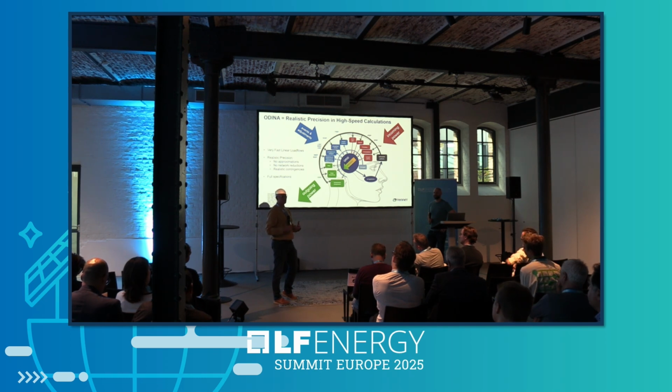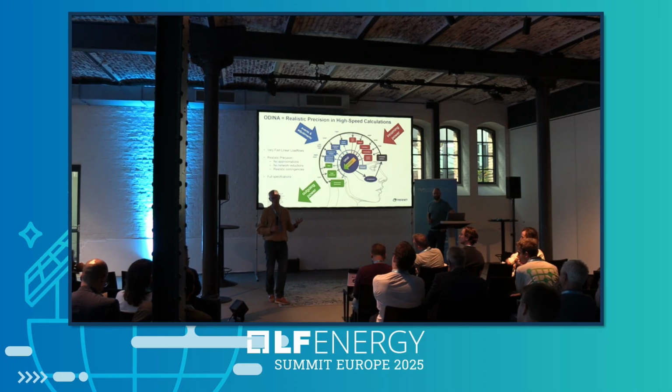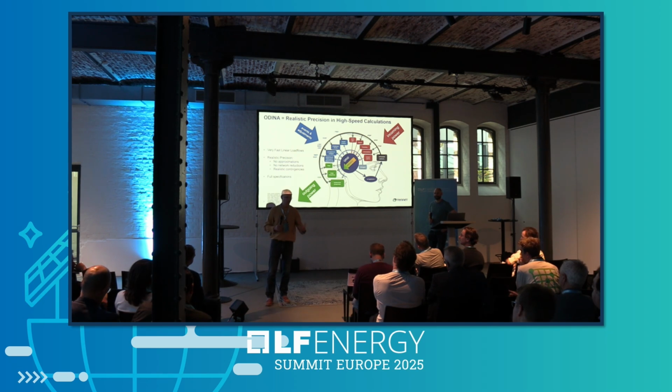So we have realistic contingencies where we actually do this failure effect analysis and take out the parts that are affected by this fault. So we have faults in the network and not outages for unplanned outages. We're analyzing the effect of the fault and not just single outages. Yeah, like PowerFactory does. Yeah. So that is the realism that we have there, and for the rest we don't make any approximation. It's just we do a linear load flow, but that's it. The rest is realistic. That's why we call it realistic precision.